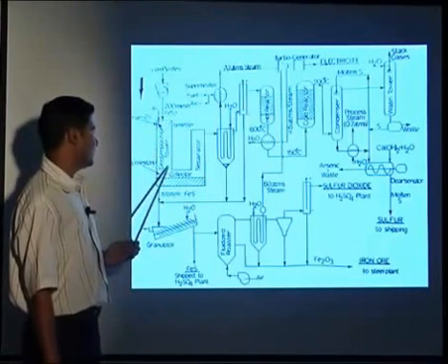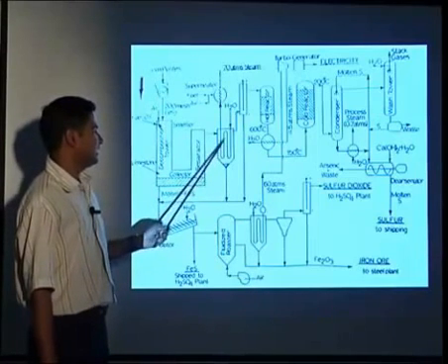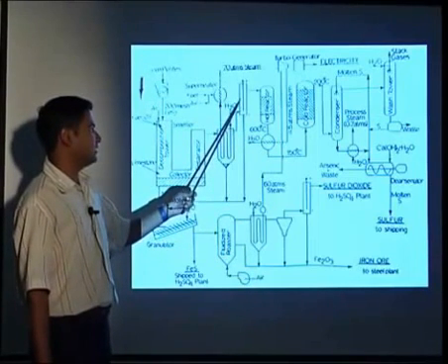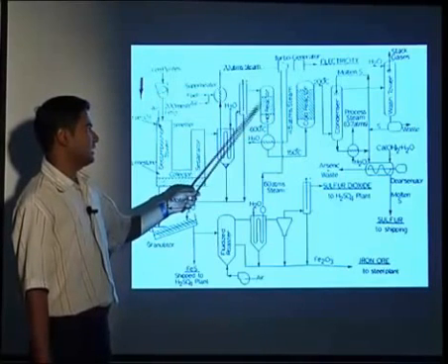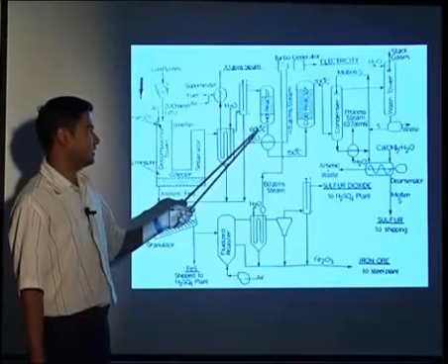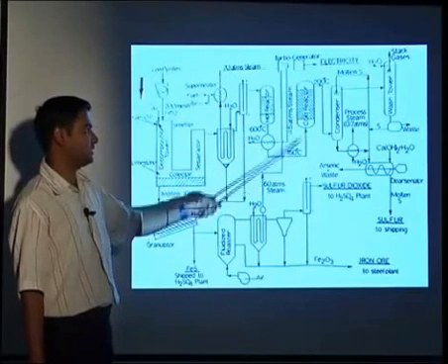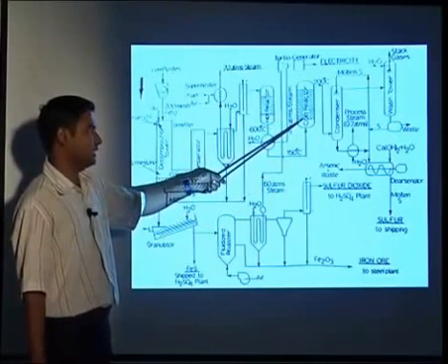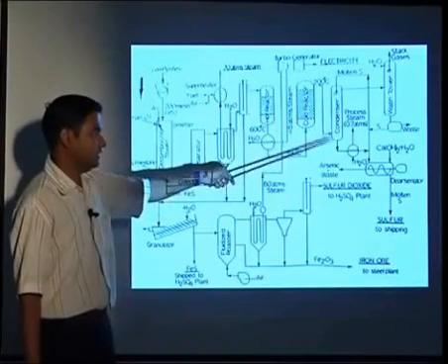So here the iron pyrite we are milling to 200 mesh. FeS2 we are feeding to the decomposition tower, and the gases we are feeding over here, then we are purifying them with the help of an electrostatic precipitator to clean the flue gases, and then we are feeding to the hot reactor at around 600 degrees Celsius, which is cooled down to 150 degrees Celsius and fed to the cold reactor, and the sulfur which is formed is condensed over here.